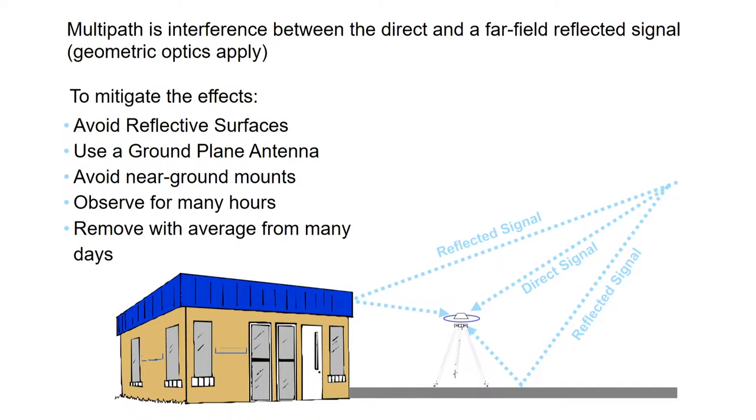Due to this cycle slip, signal loss takes place. It can be restored, and there is a module for that. In the GAMIT module you can restore all those cycle slips, and then you can process this data efficiently. Sometimes we restrict the low elevation satellite data: when we acquire the data, we give a masking of 0 to 5 degree or 0 to 10 degree. When the satellite is present there, it gets masked and doesn't get recorded into the data. Then we get less multipath and less signal loss in our data.